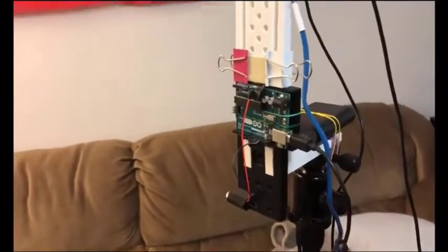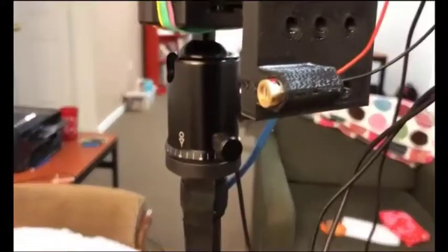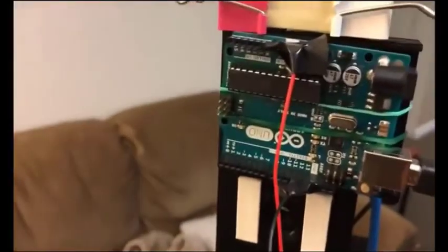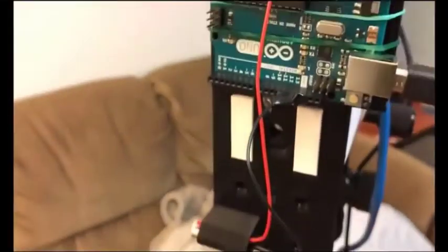Alright guys, so I'm going to go over my LiDAR setup for ENME 49Y. We can start off with the transmitter, which is a red line laser here, powered by a 5-volt Arduino. I just used some electrical tape to hold down the ends of the ground and the power. This is connected to the Raspberry Pi, so the Arduino is powered by the Raspberry Pi through a USB cable. The Raspberry Pi is also responsible for the receiver, which is an 8 megapixel camera, tied down here with some hair clips.